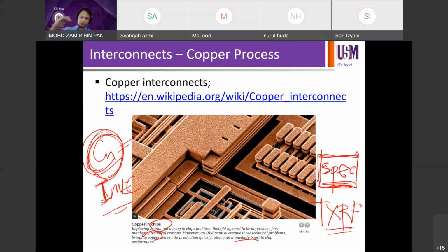Kalau dia punya level tu close to the spec, close to the limit, then you have to redo the cleaning for like 1-2 hours, then run test wafers through the equipment, verify, see the latest level of copper and the rest. Okay, then only release to run conventional technologies. This is the operation and the logistics side of running different technologies on one equipment, because you don't have the money to spend on other new equipments just to run copper where the volume might not be big. Okay, so instead you just run multiple technologies, copper and non-copper, on the same equipment, and you have to impose procedures to be able to control cross-contamination.